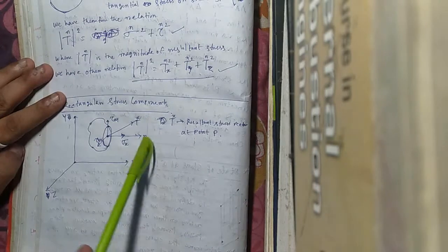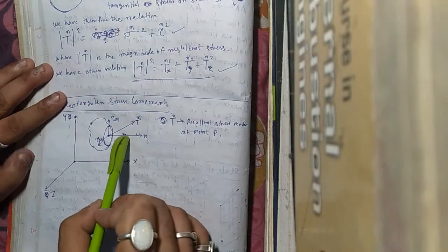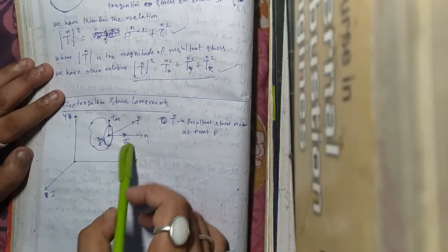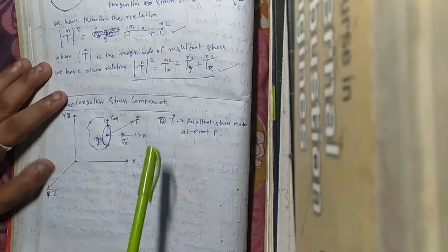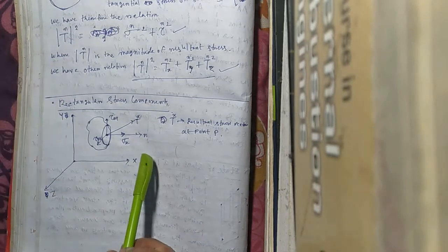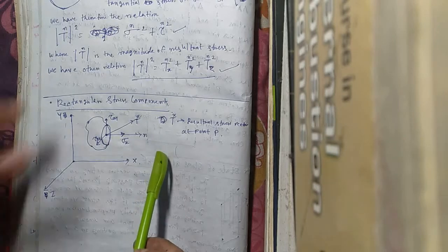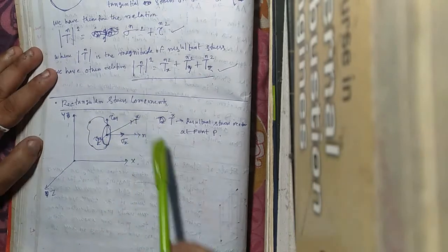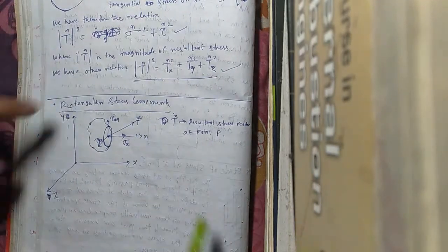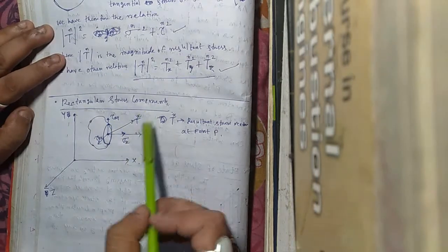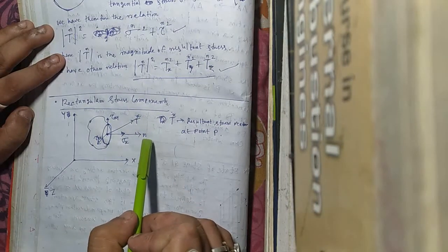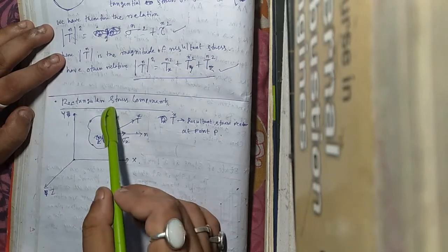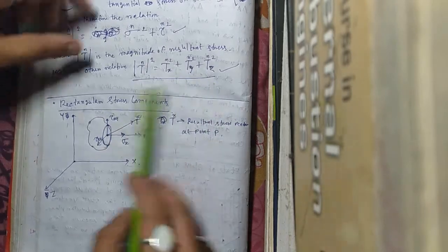Similarly here, the stress component which is along the direction of n is the normal stress, denoted as sigma x, as its direction is along the x-axis, and the other stress components along the y and z axes are known as shear stresses, because they are perpendicular to n, and these are denoted as tau xy and tau xz.